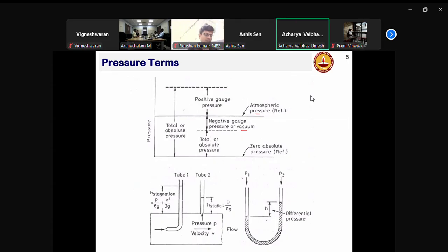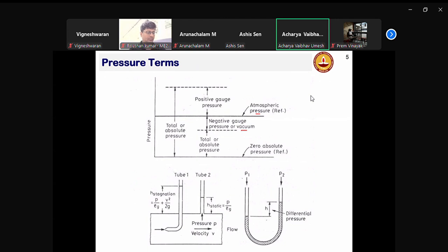Sir, suppose in the manometer we have two different fluids. Okay, so the working fluid, you don't have only one fluid, you have two different fluids. Yes, and the densities are different. I got it. So basically, now it has become a composite manometer system. So there you have to consider, but still the pressure balance should hold true. Let's say you have one more liquid here. Whenever you have a pressure difference, now it becomes a stacked system.